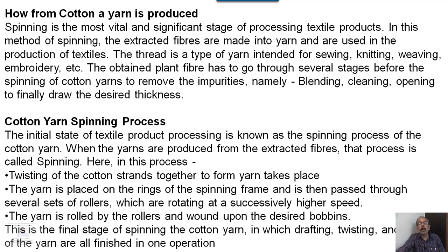This is a brief outline: the fibers are ginned. Whatever seed fibers are collected from the plant, the field, they are ginned, then converted into bales. The bales are transported to the spinning mills after properly grading them. Then a certain program is required to be evolved and kept in the spinning department, which in today's situation is normally called bale management, which is given by Worcester again. Bale management, cotton mixing program or raw material management program, under these different headings these things come.